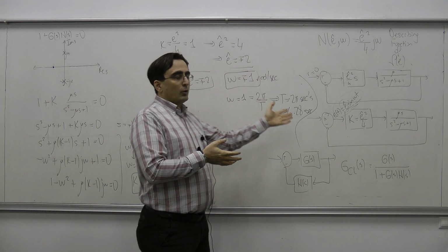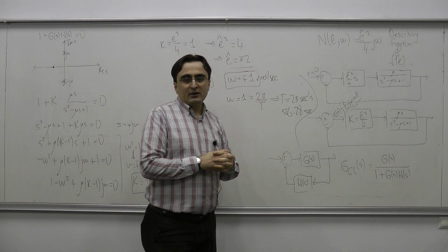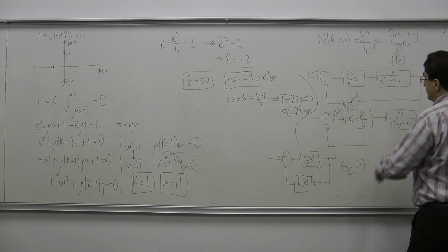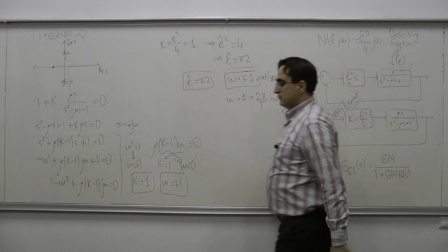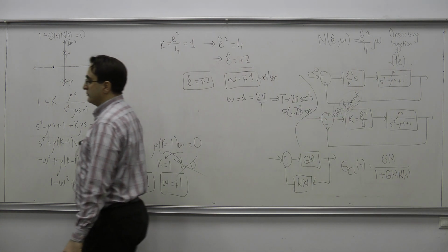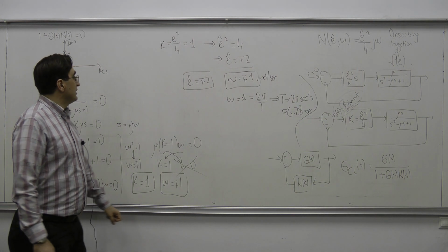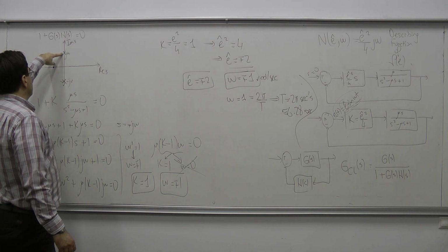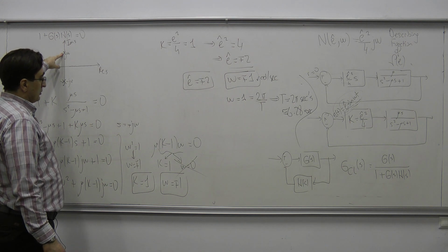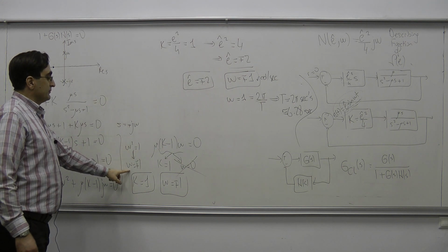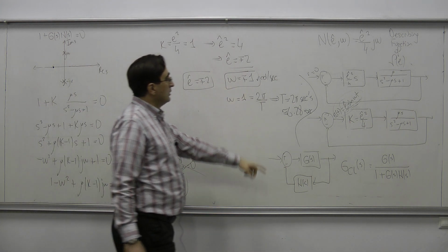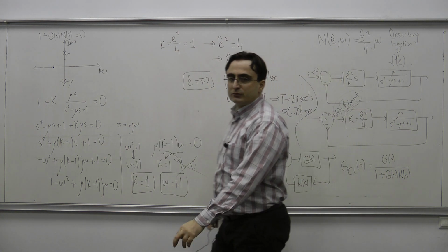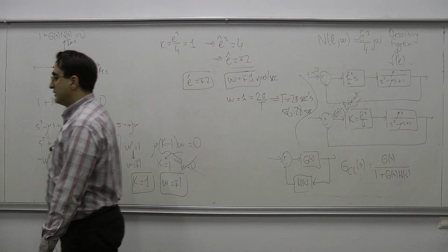Then we obtained a linear system at the end, and we enforced that system such that it has closed loop poles on the imaginary axis. The imaginary part of those closed loop poles would be the frequency of oscillations. We have identified it as either plus 1 or minus 1, and we have also found the possible amplitude values.